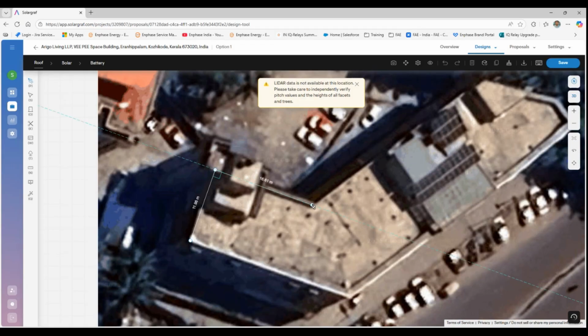Now once you click your line, you will see the blue lines here. It is a guideline. It is saying that your line is 90 degrees to the previous line. If you move a little bit, you will see it drawing a perpendicular to that line. A little bit more, it's 45 degrees. So let's go 90 degrees to this line.